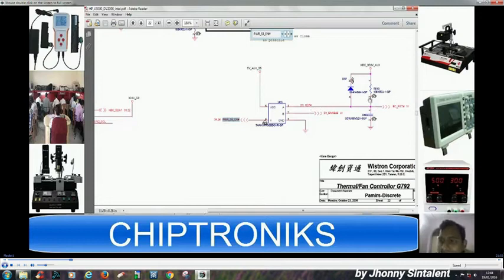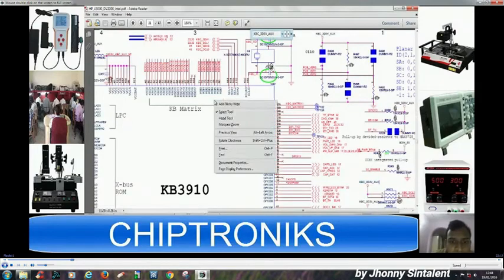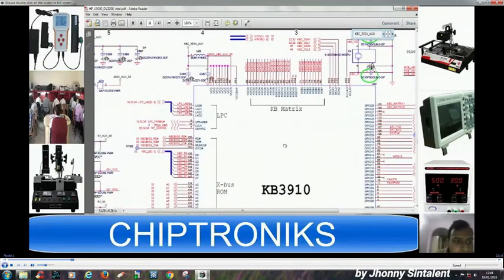Now what is A? A is EC reset, and EC reset is generated via this 3.3 AUX. This is already generated, and we can see from where this KBC_3D3_AUX_S5 is coming. We'll just copy it, paste it, and find where it is coming from.